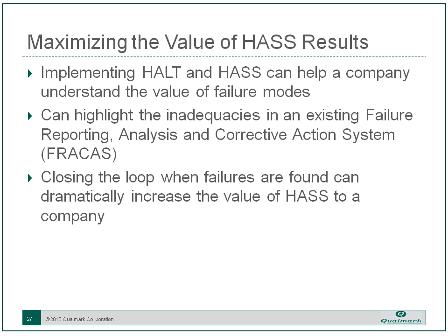And now I'd like to talk some about maximizing the value of the HASS results. And this is almost a philosophical shift that can come into a company when they have implemented HALT and when they have implemented HASS, and you begin to realize how valuable a failure mode is. To have a failure mode in your hands that you can look at, understand, and eliminate is like a piece of gold for your company, because it gives you an opportunity to make sure that those failures don't get in the customer's hands.